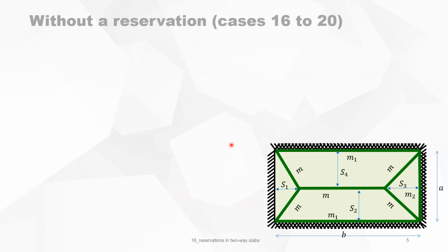Now let's have a closer look at the yield lines. For the negative bending moments, we have M1 and M2. You can calculate what M1 is regarding the positive bending moment. But the easier way to do it is that the bottom reinforcement of the slab is most of the time equal. So you can easily state that M is equal to M1 is equal to M2.